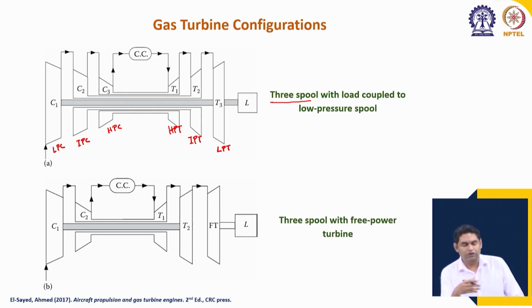remains similar to all the problems that we have solved previously. We just have to go step by step and find the temperature at each point. Okay, so starting from the inlet, say for the example, then the temperature here, then the temperature at the next point, and like this we go on, and then we can find the enthalpy changes. From that, the work input to the compressors and work output of the turbines.